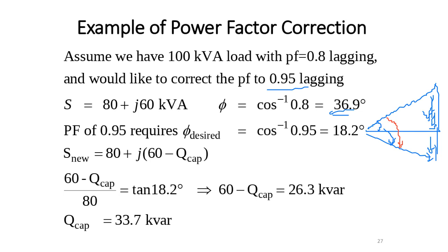All right, so what's the idea here? What do we want to find, first of all? This is a lagging power factor 0.8, and this is S. When you see that we want to improve the power factor, it means we want to play with the reactive power. We want to decrease reactive power. Therefore, it comes to your mind that I want to see what the current reactive power is from S. How do I find it?